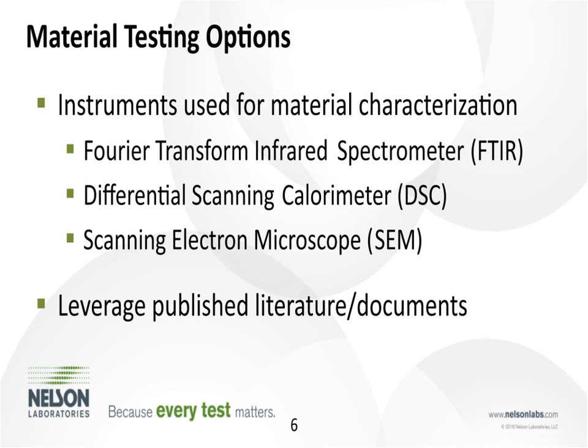So shown here are just your basic common test options. Now there are more than this, but these are instruments that really look at the physical characteristics of your material. It will not give you a quantitative amount of a chemical coming off of the material. These instruments are used to define things like durometer, glass transition, roughness, stuff like that.